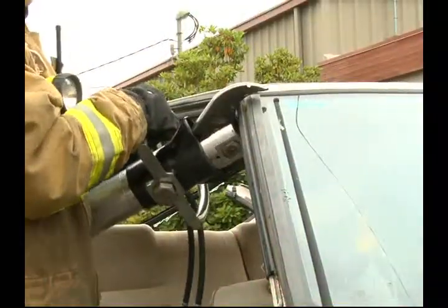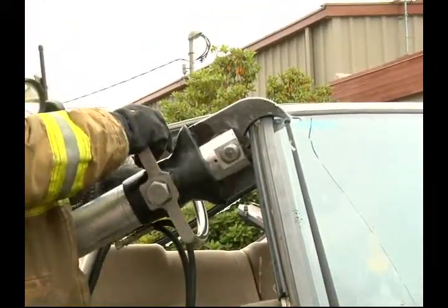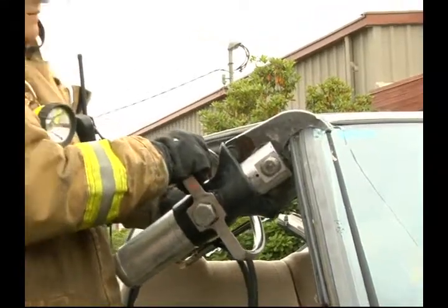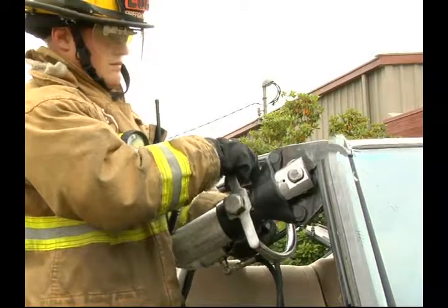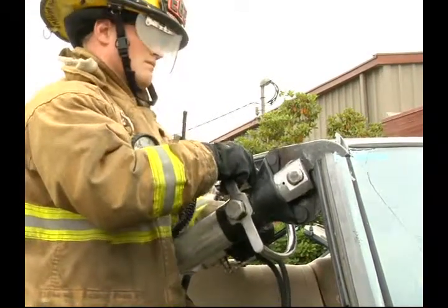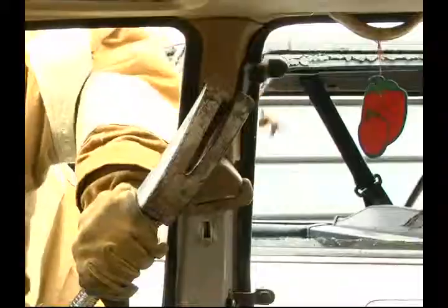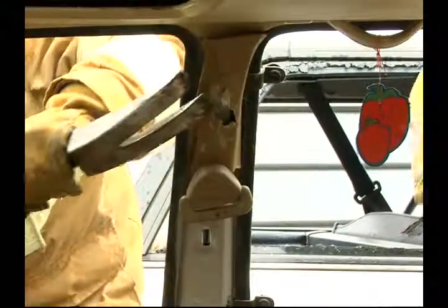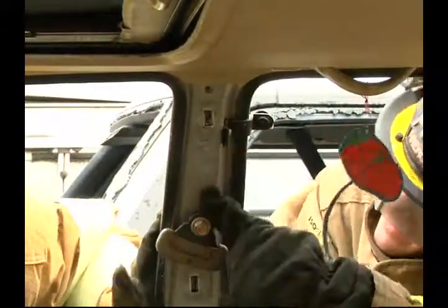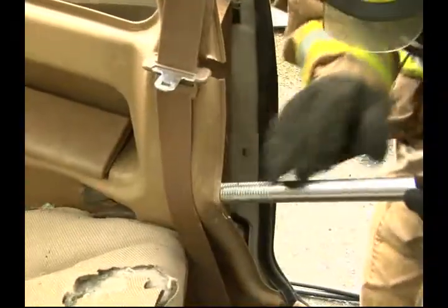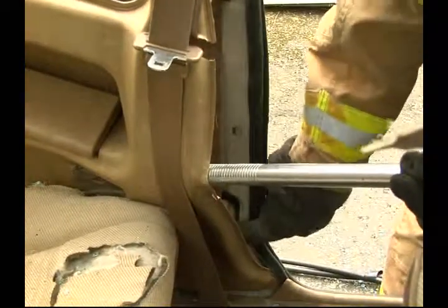Another option is to perform the same technique, only backwards. Instead of bending the roof and flapping it toward the rear of the vehicle, you will flip the entire roof with the windshield still intact over to the front end of the car. Again, it is very important to note that this is where pressurized gas cylinders are stored. Pay attention to the markings you made to locate these cylinders earlier on in the size-up.